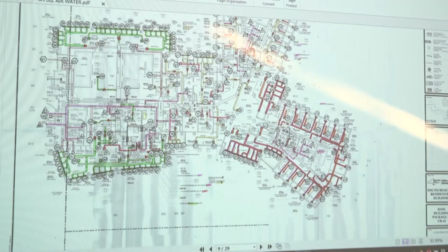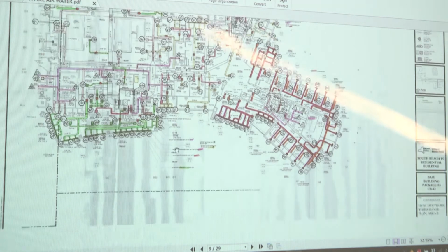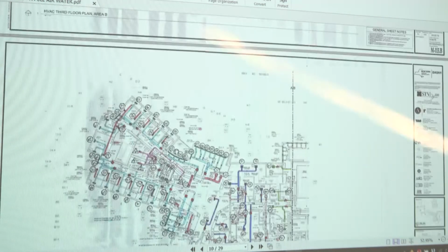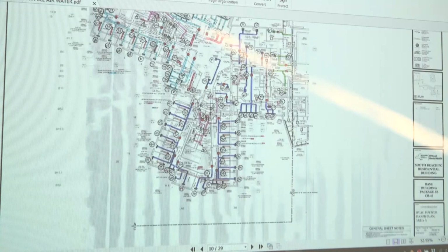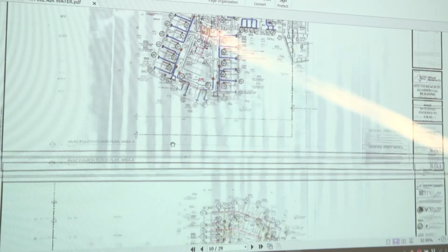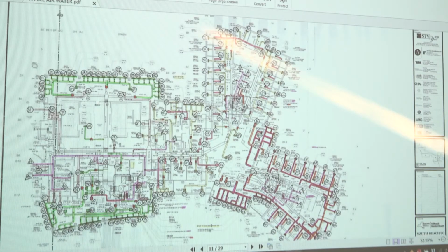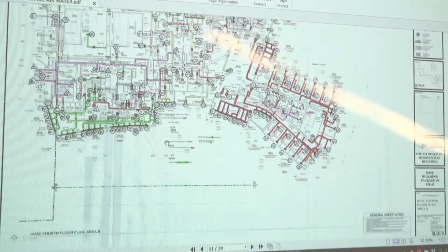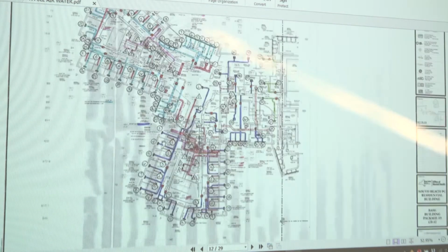I will provide these documents for your use, okay? The VAV boxes like we spoke about. Air handling units serving VAV boxes with reheat coils. Air handling units will discharge and maintain certain temperatures, okay? And then the tempering of each zone will be performed by its relative VAV box with reheat coils.